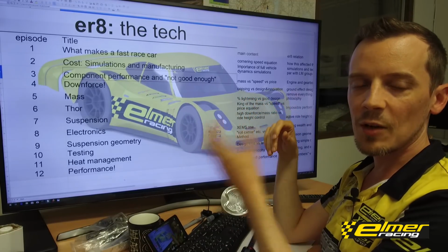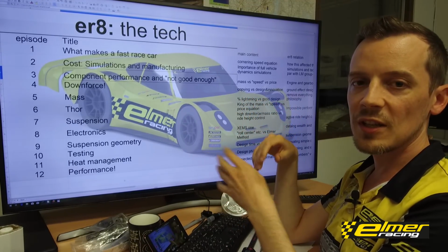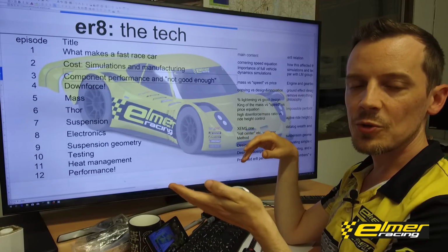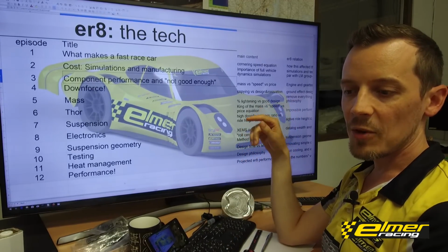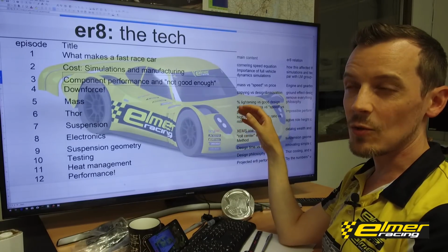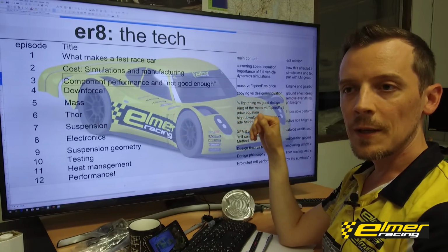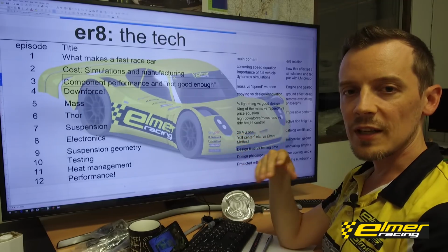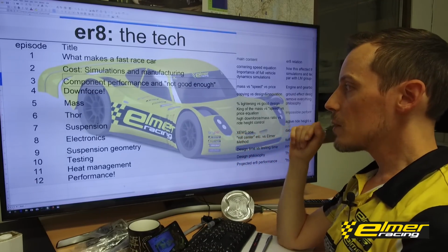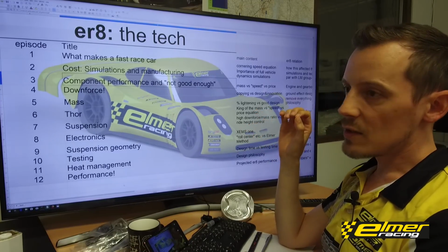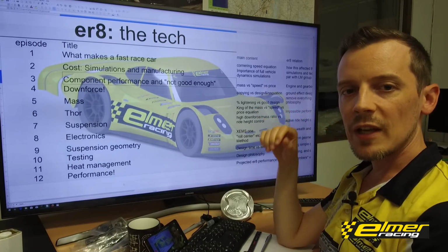So you would want the gearbox at the back of the car with the differential to help spread out the weight distribution. And with this time attack stuff and the aerodynamic rules, you definitely want a front engine or sort of front mid engine to be able to create clearance for the ground effect tunnels. So we started looking at different transaxles that were available.